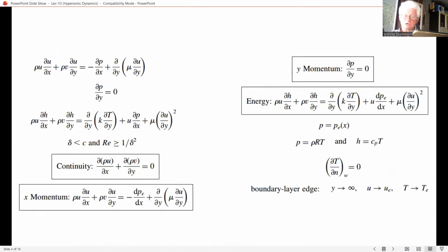In the modern world of hypersonic aerodynamics today, exact solution of the boundary layer equation can be obtained numerically for arbitrary pressure, and hence velocity, gradients external to the boundary layer. And here the word exact is being used in the same computational fluid dynamics sense.